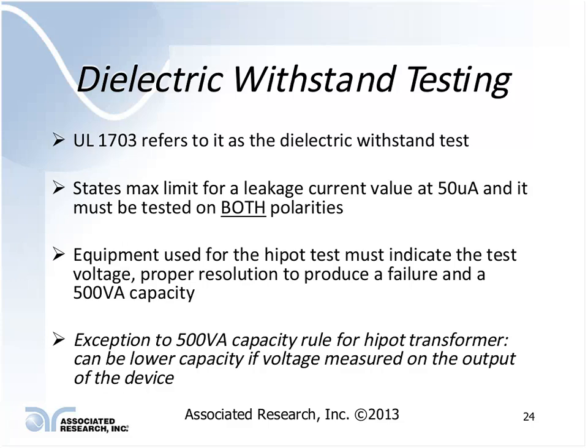So that's something to keep in mind. We've had customers call us and say, hey, I need a 500 VA unit, do you guys have one? And we get into the discussion and we find out they're testing solar panels and we say, Mr. Customer, if you look at this exception to the UL standard, you can see you actually don't need one. All of our Hipot testers have a regulated output. And it's not just our Hipot testers. I think most of them on the market right now have a pretty well-regulated output. So this exception for the UL standard can be applied to most Hipot testers out there. The IEC standards don't specify such a regulation with the 500 VA, so it really doesn't apply to those.